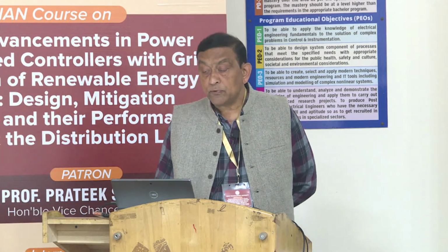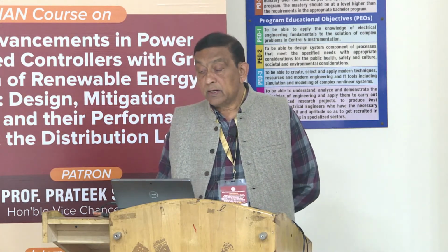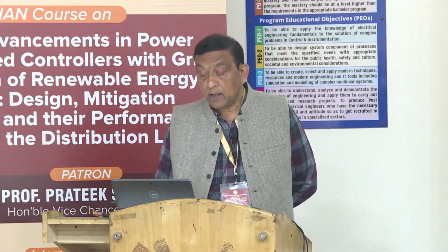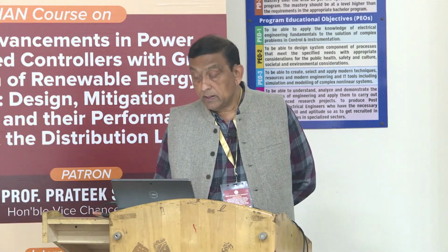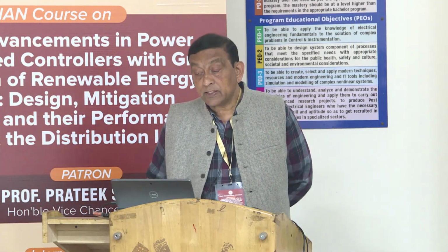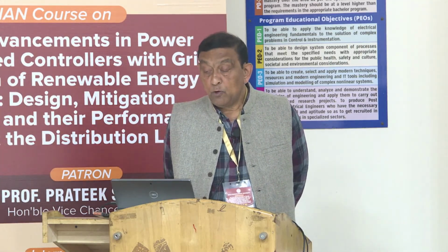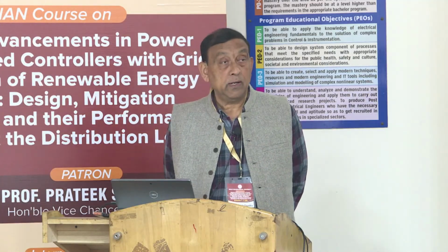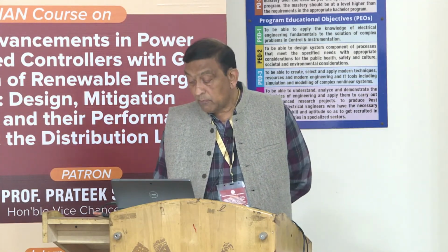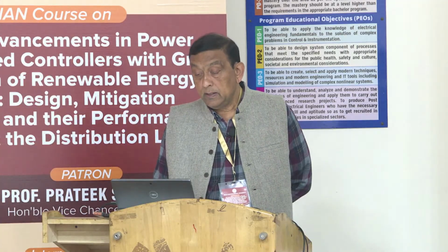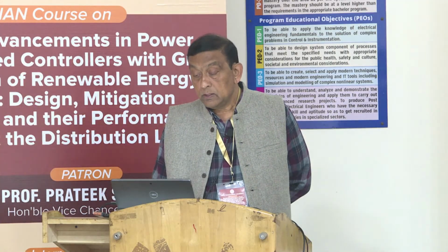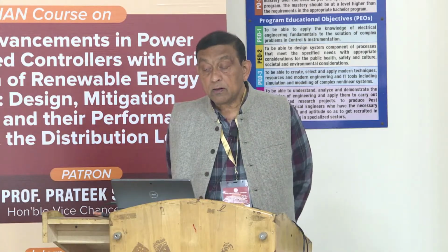Then different types of single phase diode bridge rectifiers, you see, square wave, and what harmonics are created. And if you have an RC load, a diode bridge rectifier with RC load, it causes a lot of harmonics and a lot of THD in the system.